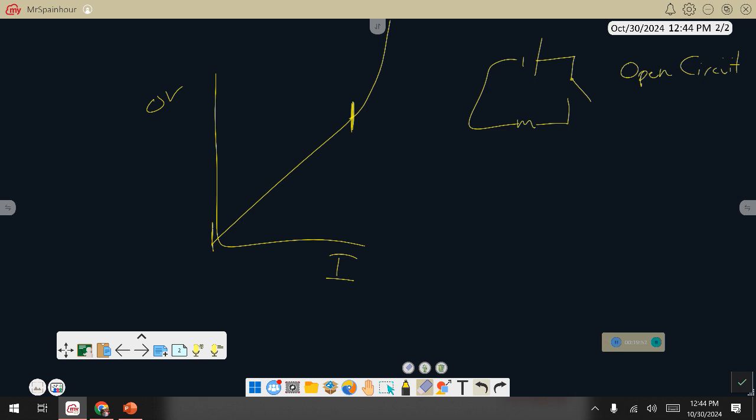Air. As you said earlier, air has a very high resistance per centimeter. So with this battery only being 1.5 volts or something like that, or even any reasonable amount, even 120, guess how much current's coming through that spot? Not very much. None. Zero. There is no current that is actually going through this system. It's kind of like having a set of tubes, and the tube is entirely blocked off at this particular point right here. So, open circuit.